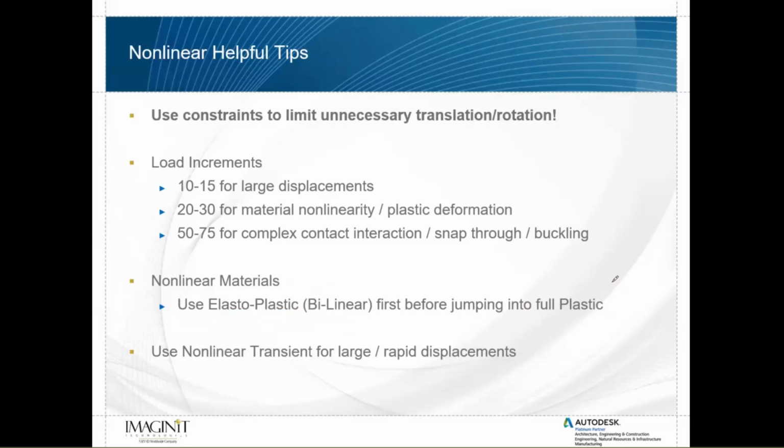And then lastly, a question came up about this a couple weeks ago from a customer who was running nonlinear static and having trouble getting a result. If you have a large displacement that happens rapidly, let's say you're applying a force to a component that's pretty unstable, so it's going to be twisting, bending, or rotating really quickly, so that as soon as you apply the load it really starts to bend. Maybe a thin sheet metal part or a plastic component that bends very quickly under load. When that rapid displacement occurs, sometimes the nonlinear static solver has trouble.